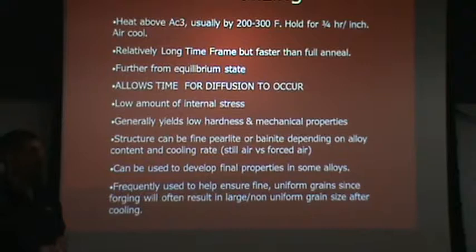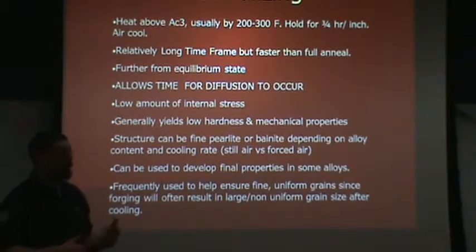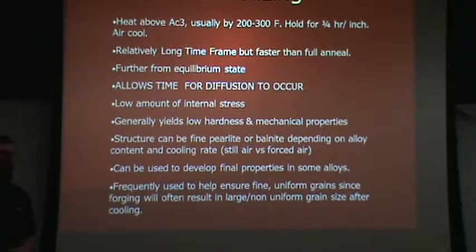But even in things that are multi-crystalline, you still will find that you'll get less creep with bigger grains. So any application where you're at an elevated temperature and you need to maintain dimensional stability will benefit from having large grains. That's the one exception to what I had said previously.